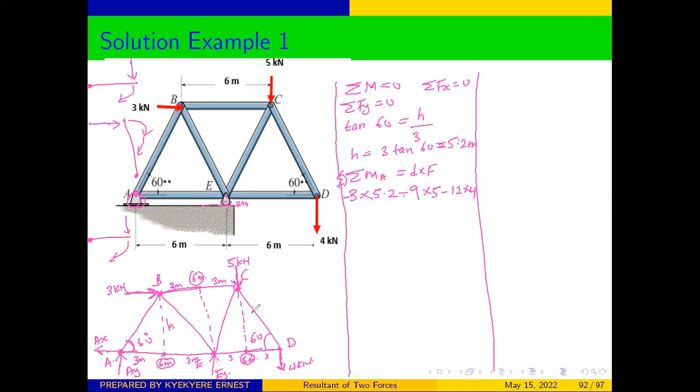And then we have our EY, which is pointing up here. This is a vertical force. Therefore, the perpendicular distance will be from this point to that point, which is 6. Therefore, that will give us 6 times EY. And will it be clockwise or anti-clockwise? This is our distance, and our force is applied here, and this is where we are taking our moment. Therefore, this force is going to rotate the object in this direction, and this direction is anti-clockwise, which should be positive, and this will be equal to 0.